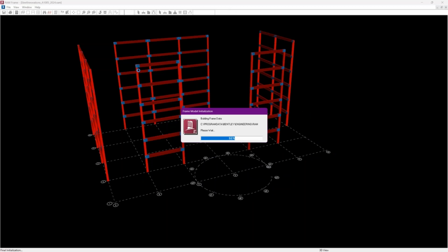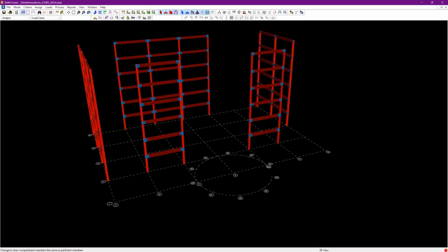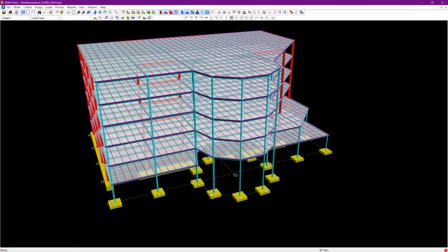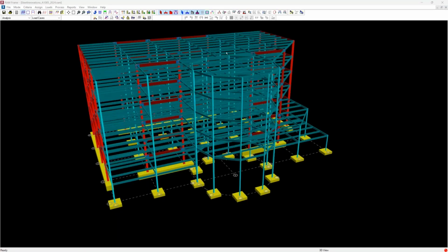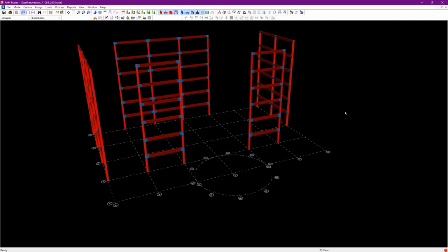If you're not familiar with the RAM Structural System, the general workflow is to design the gravity framing first, then to perform a lateral analysis on the lateral skeleton. In this case, you can see that we have this fairly complicated model with hundreds or thousands of beams in total, but many of them are just gravity beams, just imposing a reaction and providing a brace point onto the frame members. So in the lateral analysis, we don't really need all of those members. We can simplify our model down to frames that are tied by rigid diaphragms. And that's fundamentally one of the things that we've always done with the structural system. So that's my lateral model, that's my finite element model.